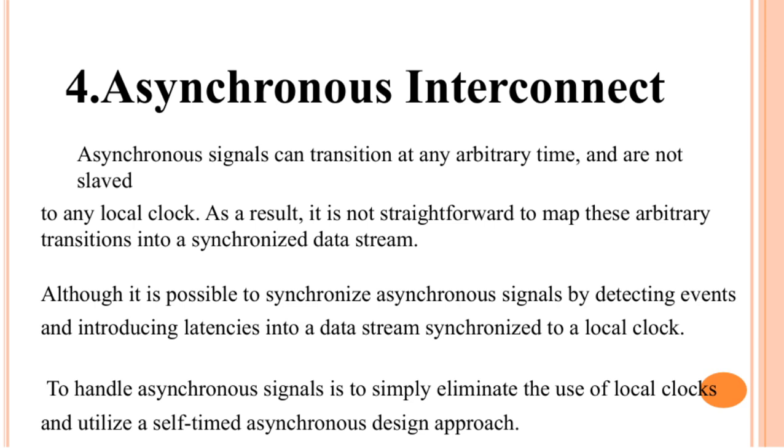One common approach to managing this is to detect specific events within the asynchronous signal and then introduce some delay or latency, so that the data can be aligned with a local clock. Essentially, this tries to bring the asynchronous data into the synchronous domain by adding timing buffers.